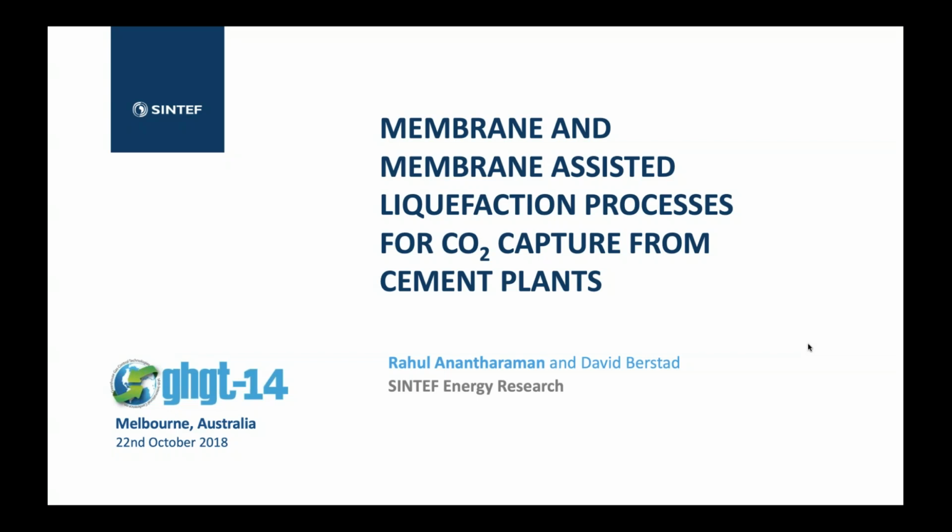So in this work, what we're going to be doing is identify what are the membrane properties that are required for the membrane-assisted liquefaction process to perform better than what we have seen thus far in the SEMCAP process, and compare it to a two-stage membrane process for CO2 capture from a cement plant.